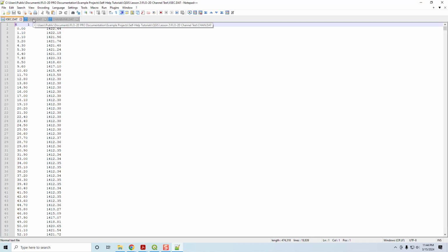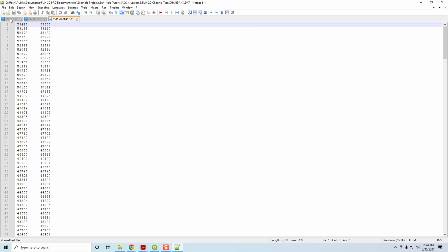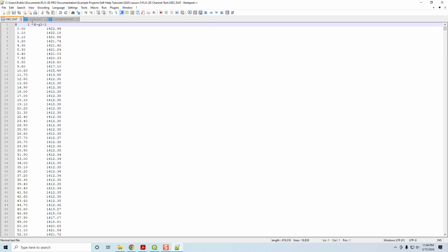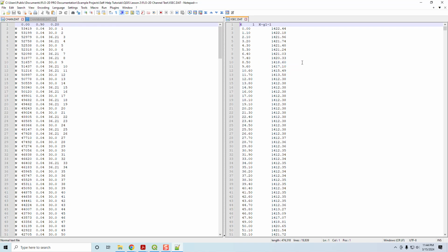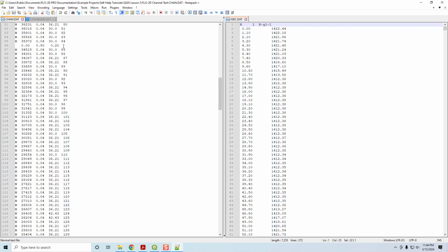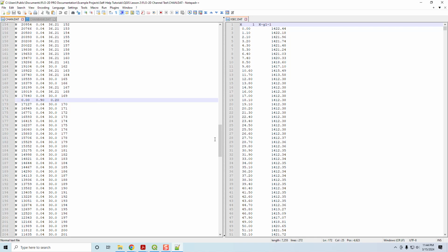And then you saw in the previous RAS export, you saw these files already, but let's go over them again in case you didn't do the RAS export. So we'll pop this one over on this side, and this one stays here. So these are your control lines. You get one for every new channel segment. So we should have 3 of those control lines because we have 3 channel segments.